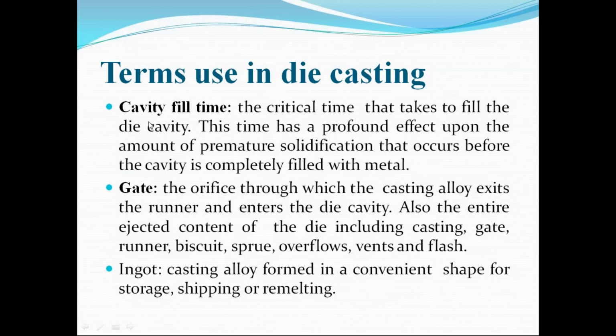Now the next one is cavity fill time, the critical time it takes to fill the die cavity. This time has a profound effect upon the amount of premature solidification that occurs before the cavity is completely filled with metal. The process is: first liquid material fills the shot chamber, then we apply the plunger, and it travels through the gating system, ultimately to the cavity. That total travel needs some time, but what will be the time? What is the best practice for calculating the time? Is it very high or less?